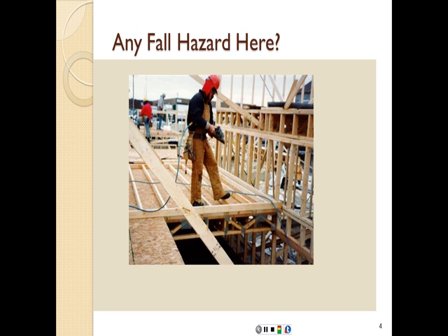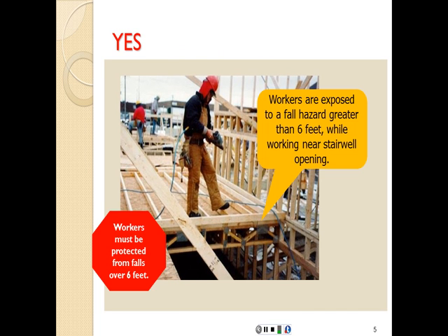Here's another example. A carpenter working on some formwork, and he's getting close to an open end, and he doesn't have any fall protective equipment. So again, we can see also the power cable around him for his drill, and if he trips on that cable, he might fall, and again, that's probably at the 2nd floor level, so there might be an injury here as well.